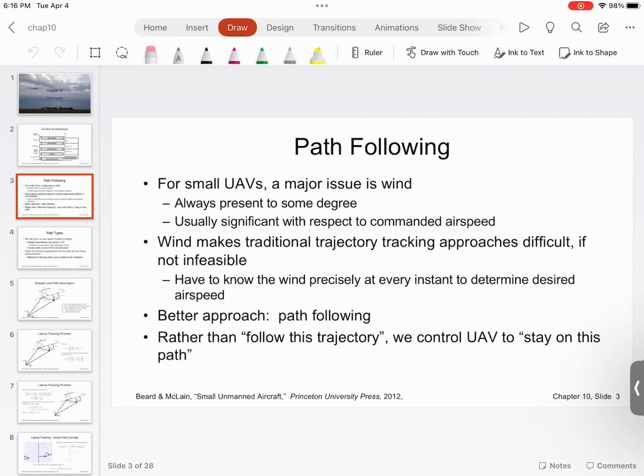In the case of flying robot, what the robot is trying to do is use a seeking approach, which means the robot is at point A. Now the robot wants to go to point A1. So for that time instance, the only objective that the robot has is to go from point A to point A1. So this is something similar to waypoint following. What that means is you have two waypoints.